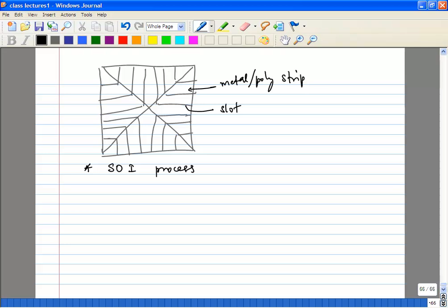If you look at Qs of a standard digital process, if you just take no extra options, no thick metal layer, nothing, you will have Qs between 5 and 10. If you go for thick metal layers, you can get maybe 15, maybe 20, and if you go for SOI processes plus all of these, you may get 25, 30, sometimes even higher. So it all depends on what you choose to do with the process, and of course your topology matters.